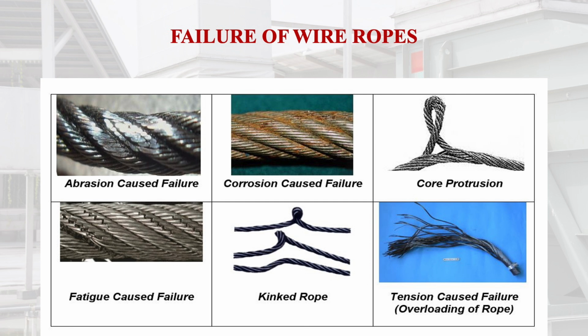Corrosion is another factor, especially in areas where there is salty water due to the sea or some other regions, or where there is a chemical plant. The possibility of corrosion is much more. If a crane is handling some chemicals, whatever the metal of the wire ropes may be, corrosion is likely to happen, and we should inspect the intensity of corrosion.